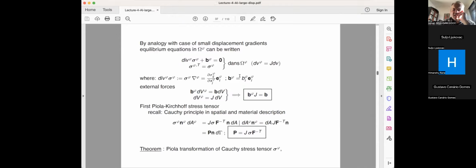Another thing which is kind of important to say: when you're designing a structure, especially structures in the engineering domain where the dead load is important, you're talking about, let's say, reinforced concrete at 25 kilonewton per cubic meter, steel at 78 kilonewton per cubic meter. But this is only the case where you have the initial configuration.